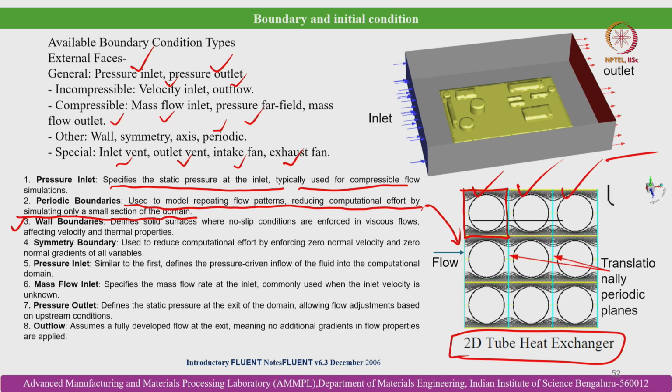Assume that there is a fluid flowing between two parallel plates. These are the two parallel plates. Then the velocity distribution takes the form like this. So, if I draw it here, it basically attains a maximum at the center between both the surfaces, and the velocity is 0 at the wall. So, V equal to 0 at the wall is the no slip boundary condition.